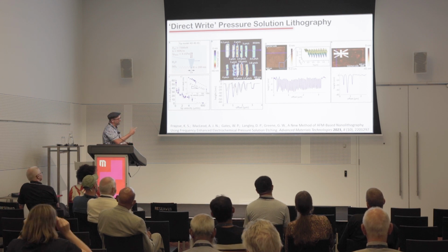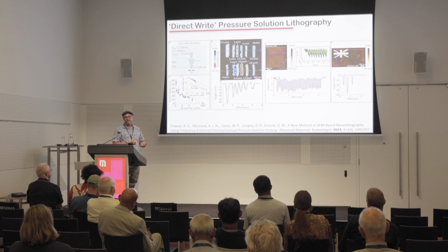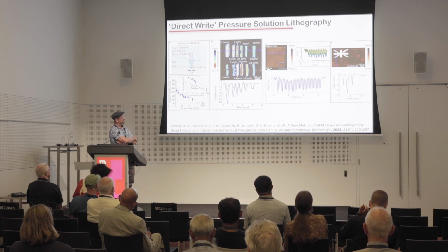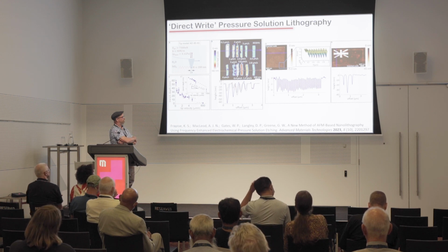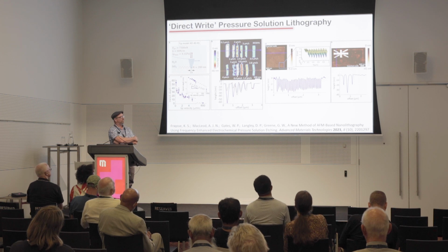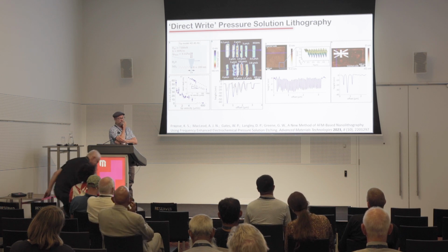The technology we have here is analogous to a technology called the nanofraser, or a thermal probe AFM. The main difference is that the nanofraser etches a photoresist material, and then you have to transfer that pattern into an inorganic substrate. Here we can etch inorganic substrates directly using this effect. The experiments we're showing here were all done in silica, but we've been able to do pressure solution in a wide variety of substrates, including sapphire, gallium nitride, gallium arsenide, silicon wafer, and so forth.